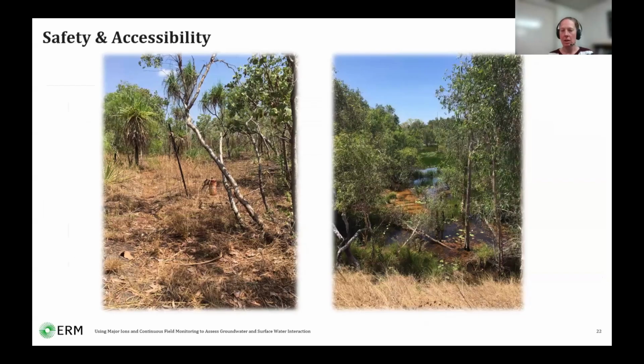Thank you. I appreciate the additional thoughts, and yeah, I was nodding along about reinstalling loggers at different levels at different times can be challenging. The only other thing I'd say before I continue on with this slide is that the other thing to consider for larger or remote sites is accurate weather monitoring too, particularly rainfall. So rather than relying on a Bureau of Meteorology weather station that may be miles away and which may be experiencing quite different weather conditions, obviously you'd need a large site, and there needs to be value in that accurate on-site weather monitoring, but it can be hugely valuable in certain cases.